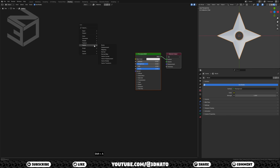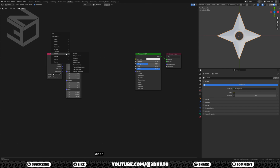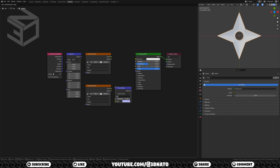Press Shift+A, go to Input, and add a Texture Coordinate node. Press Shift+A, go to Vector, and add a Mapping node. Press Shift+A, go to Texture, and add an Image Texture node. Press Shift+D, and duplicate the Image Texture node. Press Shift+A, go to Vector, and add a Normal Map node.